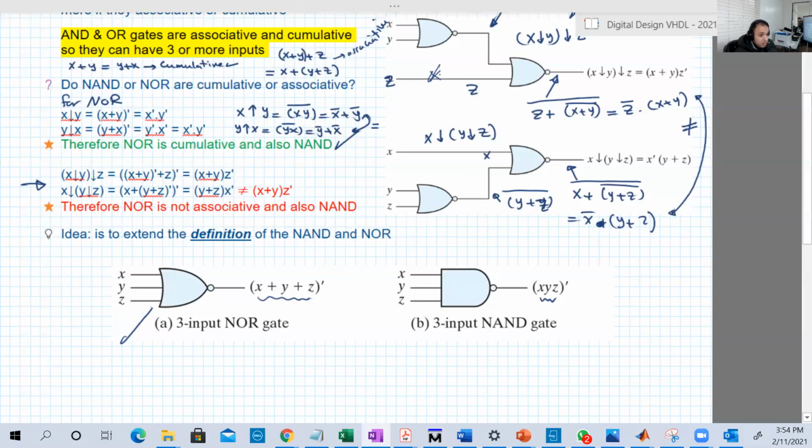So for OR, you can have a circuit that has 3 inputs and performs the function of OR. Or if you don't have one, you can use 2 OR gates, each with 2 inputs, and construct them such that you OR 2 variables together, then the output is ORed with the third variable in the second OR.